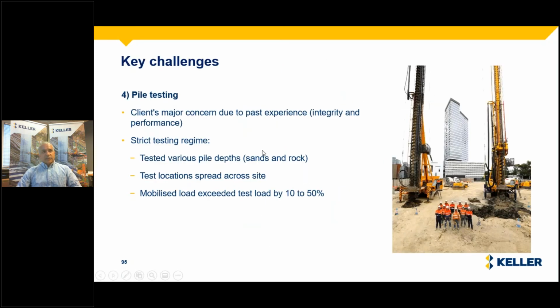Of course, the key challenge was that the past experience with the projects next door had not been great on the bored piles for that area, as in the rock formations, while drilling with bentonite, they were losing all the bentonite and having issues with dropping their hydraulic passive resistance. They decided to move into CFA, testing at different depths across the site and asking us to mobilize the load to more than 10 to 50% of the test load to accept the piles.